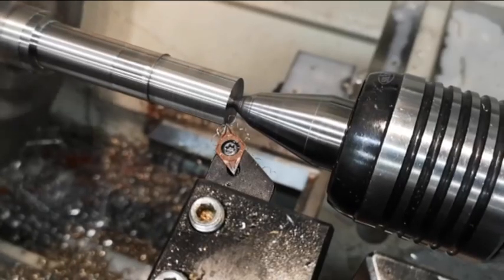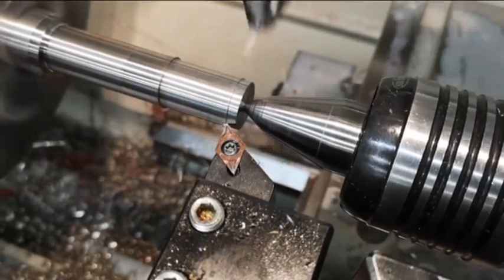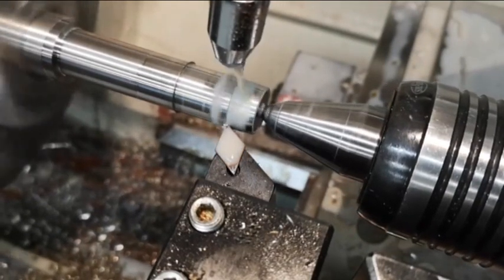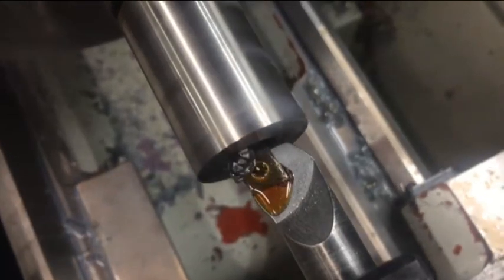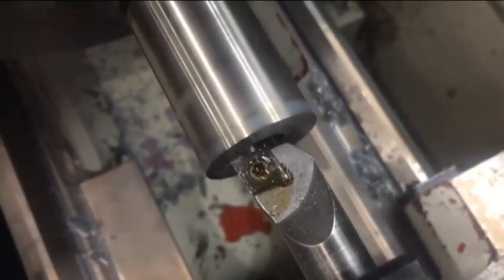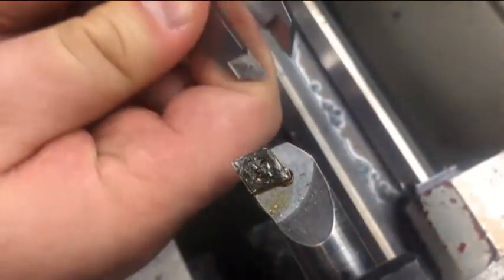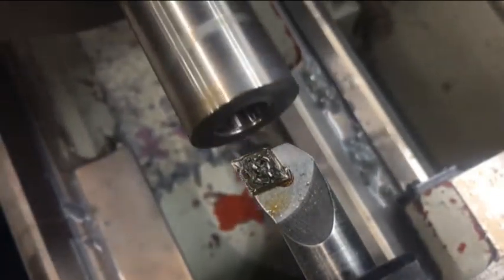Before we get any further, I should mention that I'll be talking about shafts and pins fitting in holes, but per ISO 286, this system can be used for internal and external features of size. You'll sometimes see it used for keys fitting in keyways, for example. How things fit together is determined by how much free space there is between the two parts. If there's lots, there will be lots of space for the parts to move. If there's only a little, there will be a lot less space. Finally, if there's no space, the part won't be able to move.